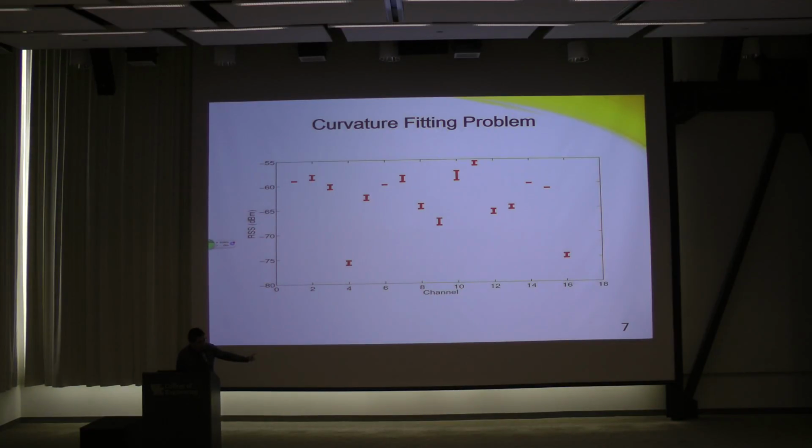This figure we measured in a real practical environment. The x-axis is the channel, the y-axis is the RSS. And we find that between the same sender and receiver at the same distance in the same environment, at different channels, the RSS is different. And we think we can get more information, such as phase information, from this figure.